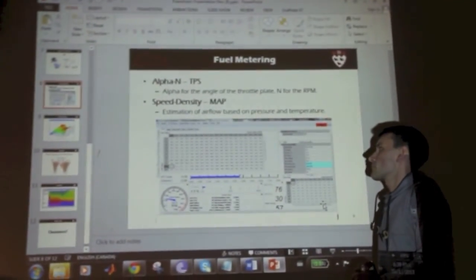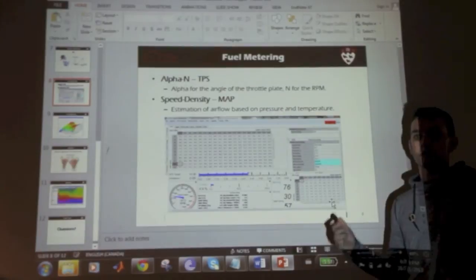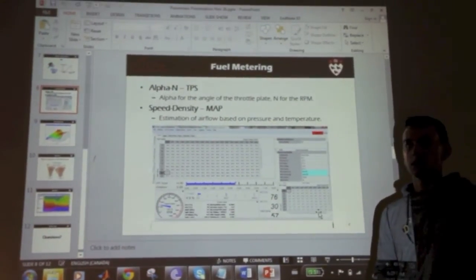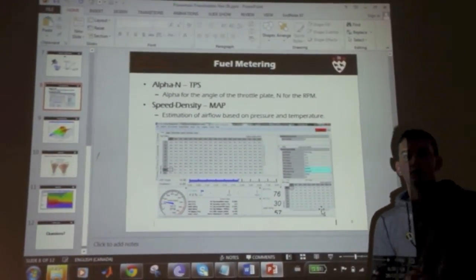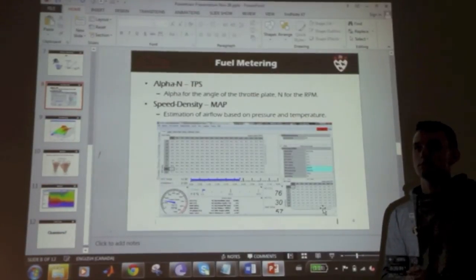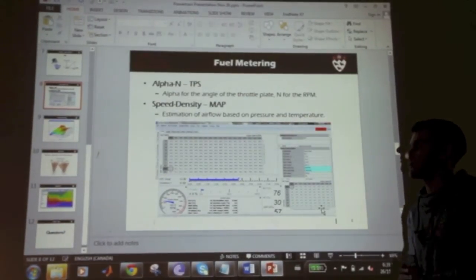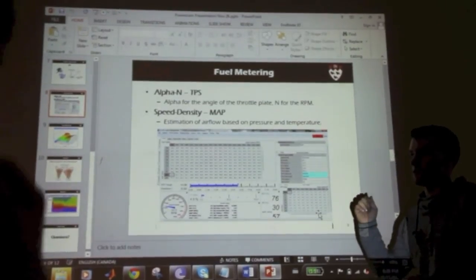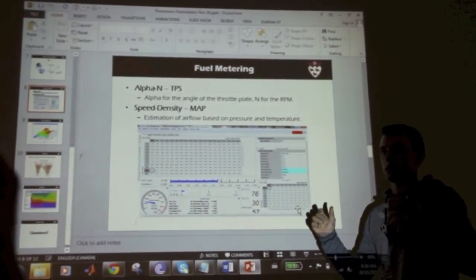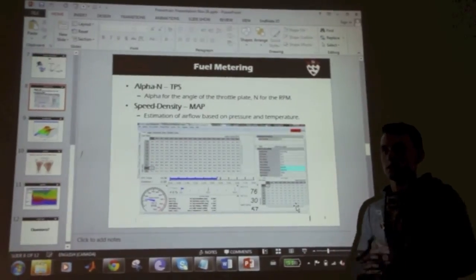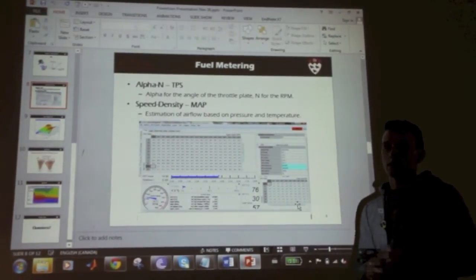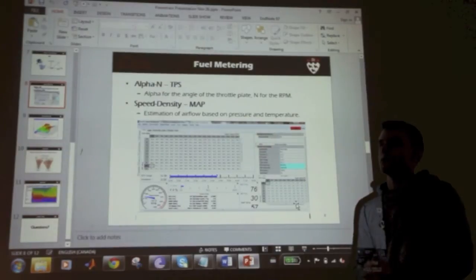Yeah, well, essentially, if we want to get into a little bit of how one actually tunes the fuel map and the emission map on the dyno, one common way, for example if you're taking power curves like we used to do at the shop on a chassis dyno, is that you define a sweep rate, i.e. an RPM increase rate, and that's controlled by the dyno computer.